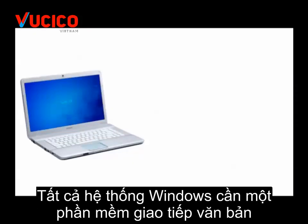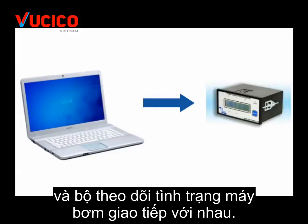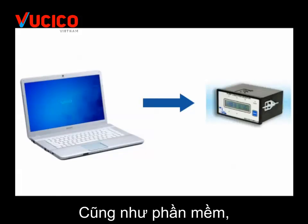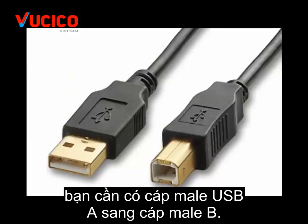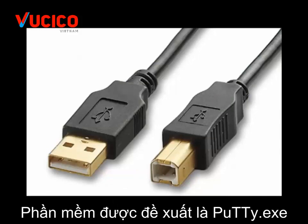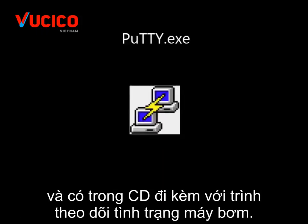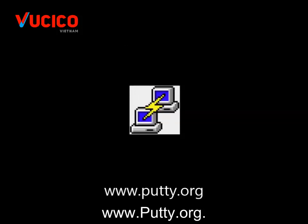All Windows systems will require a communication type software to enable the laptop and pump condition monitor to communicate between each other. As well as the software, you will require a USB-A male to B male cable. This must be connected before any download can begin. The software recommended is PuTTY and can be found on the CD that came with the pump condition monitor. Alternatively, it can be downloaded at www.putty.org.